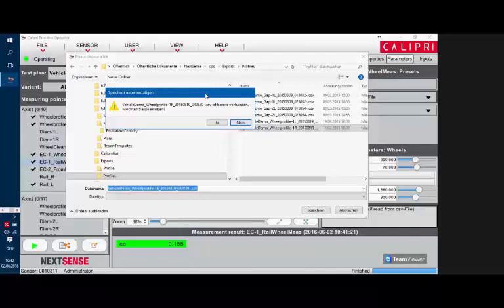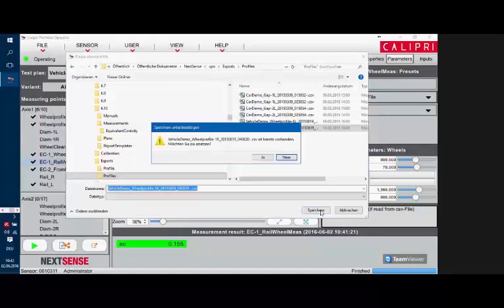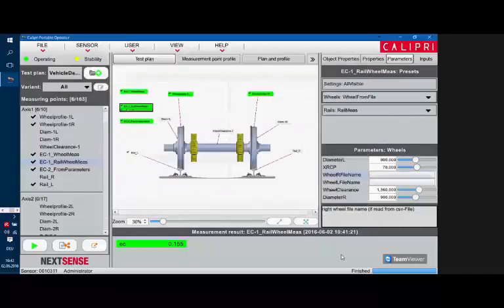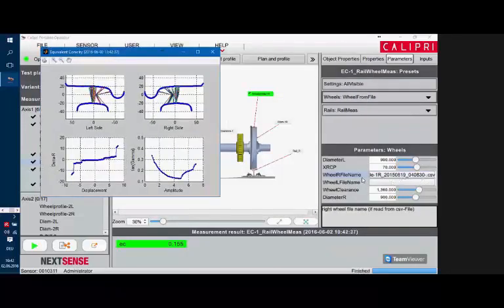If you select the file there, the dialog is asking you whether you want to overwrite. It's in German, I'm sorry. If you want to overwrite the existing file, that's just not true. It's not overwriting, it's really taking the file as an input, but the dialog is expecting to store data somewhere, and therefore it's asking you whether you want to overwrite it. Just say yes or no, it doesn't matter. Yes, it matters. You have to say yes, and then it's used. That's just due to the fact that this parameter for selecting a file cannot differentiate between storing or loading data, and it's always expecting that you want to store something. Also, you're just loading already stored data. So that's something you need to be aware of if you use stored data, because it's really confusing and it needs to be improved.